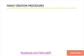So in this chapter, we're going to lay down the foundation of the skills that we're going to need to begin making fully parametric component model families. And we'll start that with just an overview of the process. So the first thing is deciding what you need. This can take the form of hand-drawn sketches, look at other objects and mark them up. You can download things and use those as a basis, whatever process you use, but you identify the need, you decide how you want the item you're going to create to behave, and you document that in some way, either through sketches or other forms.